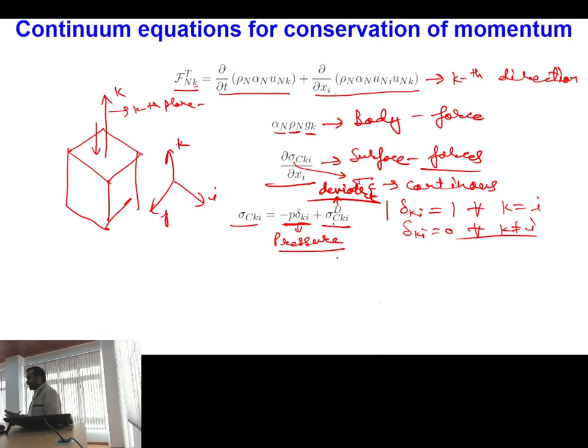That is within the horizon of this course. There can be situations of non-Newtonian multi-phase flow, but that is beyond the scope of this course. This deviatoric component, for Newtonian fluids, comes from Stokes' hypothesis, and it is represented in terms of the dynamic viscosity. All of you know that.